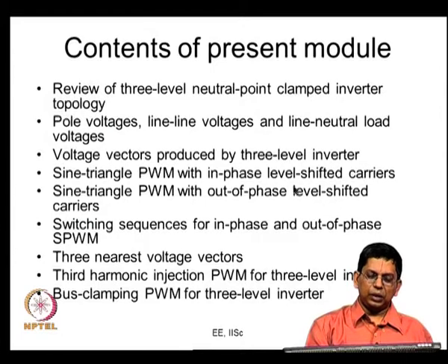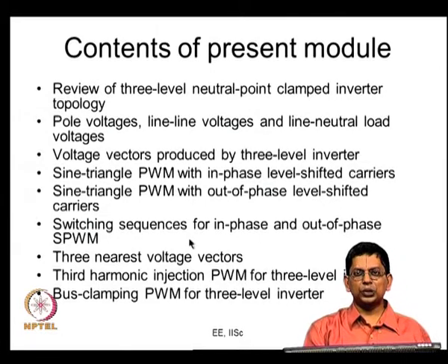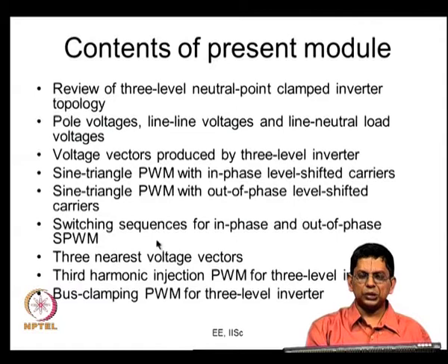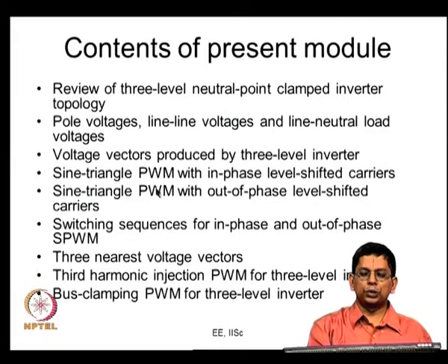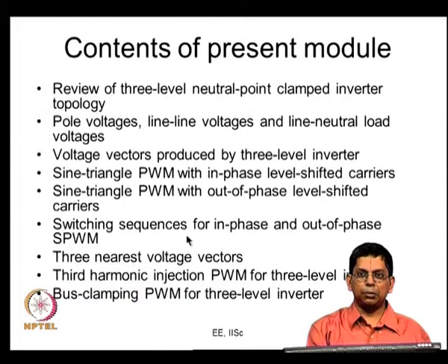Then we looked at the switching sequence. So, we want to see what inverter states we are getting. What do we mean by the switching sequence? We are looking at the states in which the different inverter states are applied when you use a particular PWM method. This is actually the link between your triangle comparison based PWM and the space vector based PWM. So, there are 2 different approaches and you actually link them nicely by doing this.